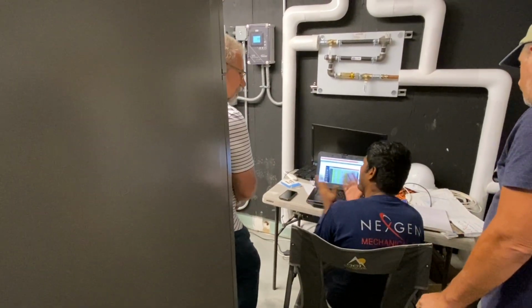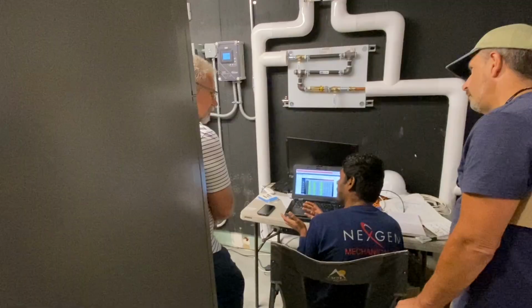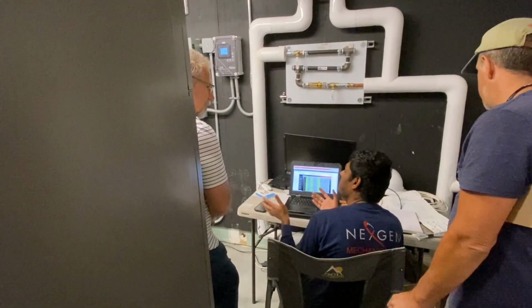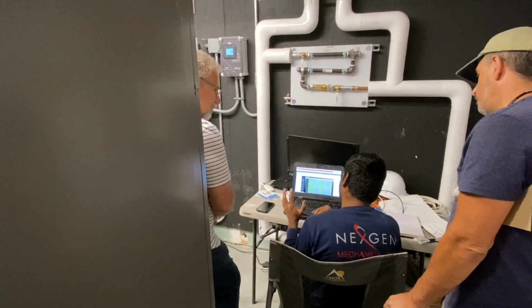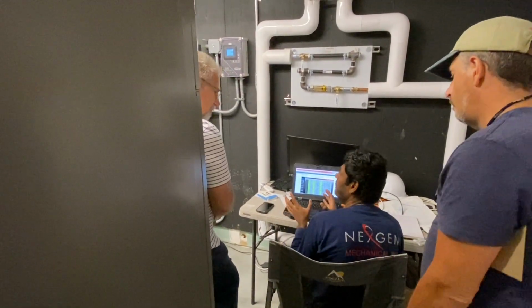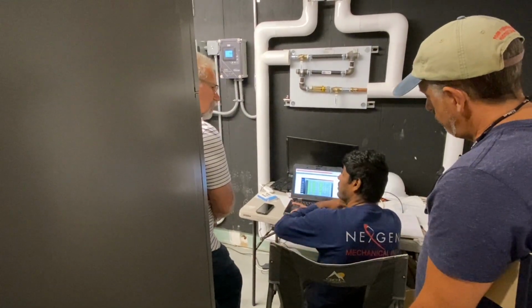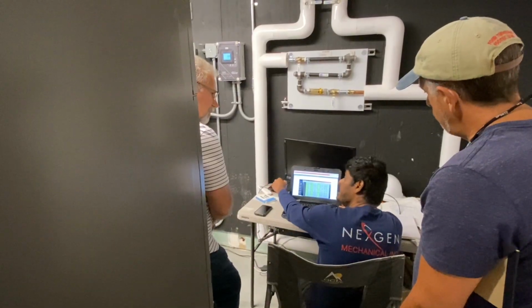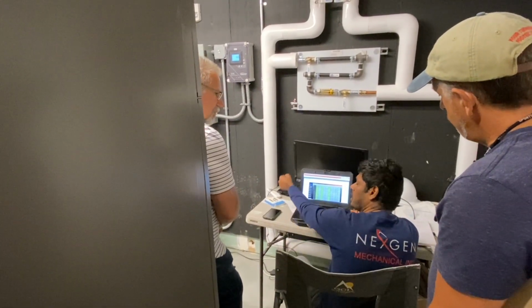The other interlock that we have between the RTU and the VAV is basically the warm up and the cool down mode. This is a very interlocked sequence. My optimizer decides based on the outside air temperature whether I have to go to a warm up or go to a cool down.